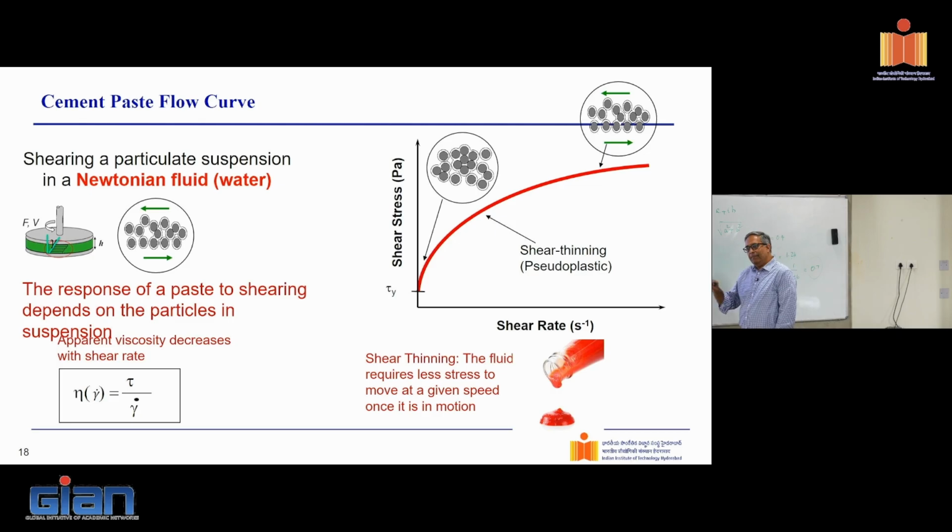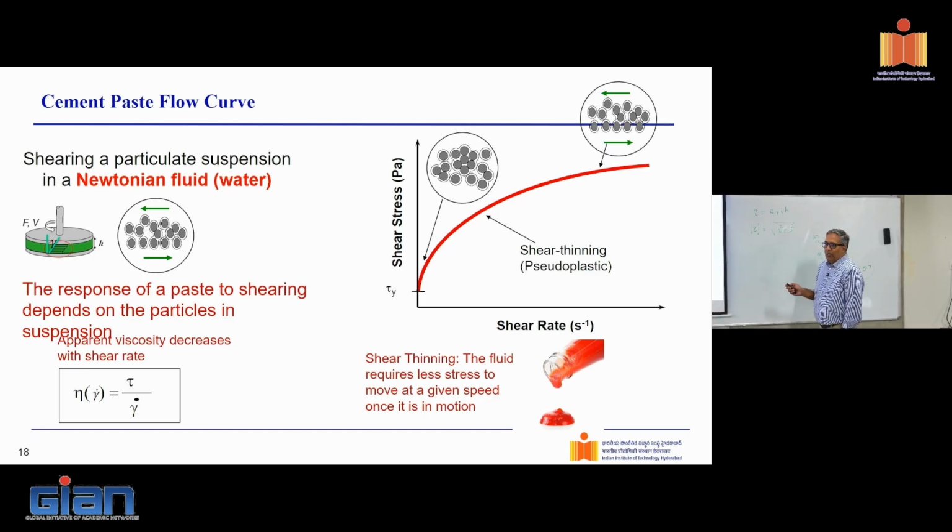It's basically nonlinear. Nonlinear in a way that if you physically interpret it, the slope of this starts to decrease as you go up. What does that mean? Basically, what that means is that viscosity, the local viscosity, is decreasing. And we call such a material shear thinning. And these are materials that if you agitate them, would tend to loosen up.